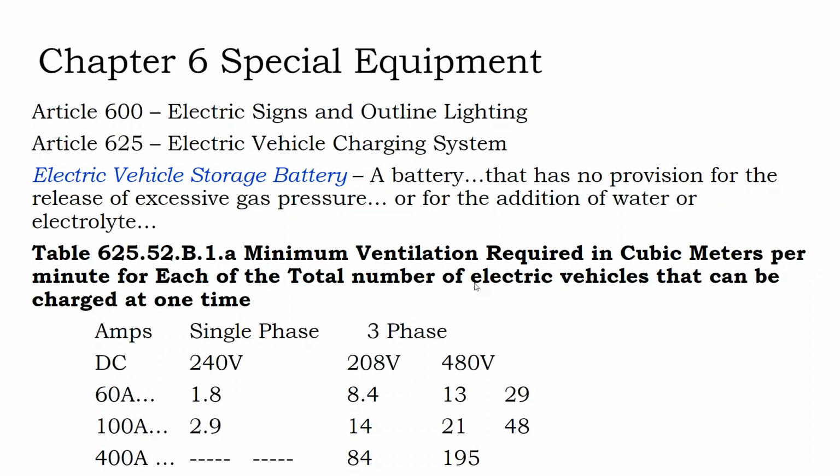It might burn for a while because the batteries, once they start going, they burn. There's a lot of power stored there to come out. And you want to be able to ventilate that air inside the room to the outside. So even though it's a sealed battery, when you get enough of these batteries in a room, you have to have ventilation in the room.